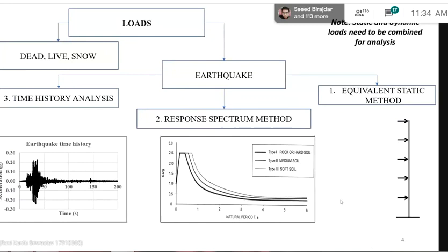But at some point, we will obtain a peak value, right? There will be a peak displacement of the cantilever beam at its top. The cantilever which we had taken has some time period, like every building or every element has some time period. There are a number of time periods, and all models have a fundamental time period. Since we have taken a 1 degree of freedom system, a single cantilever beam, if you apply the time history data at the base of the cantilever beam, it will vibrate. But at some instant of time, it will have some peak value.